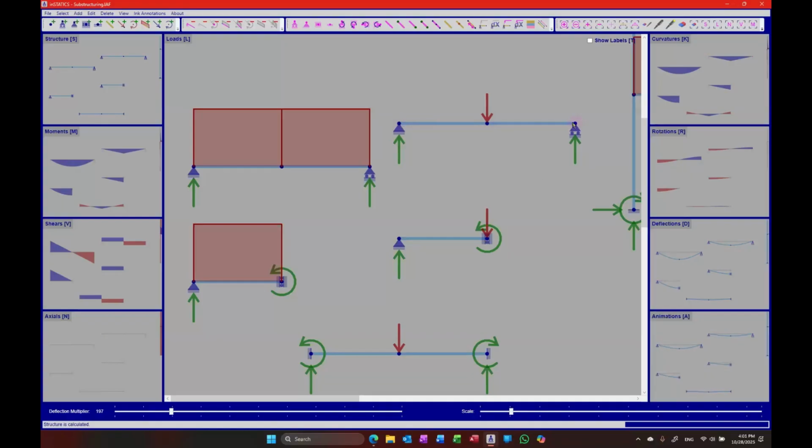Yeah, so it's going to be 9 by 9, right? My final structure matrix is going to be 9 by 9. If I can make it 6 by 6, by hand it would be easier. And if my numbers were much larger, maybe even for an older computer, it would be easier.